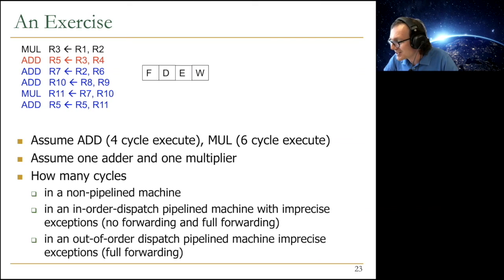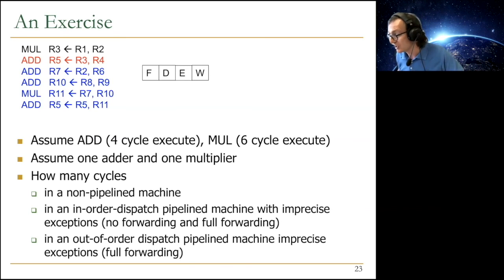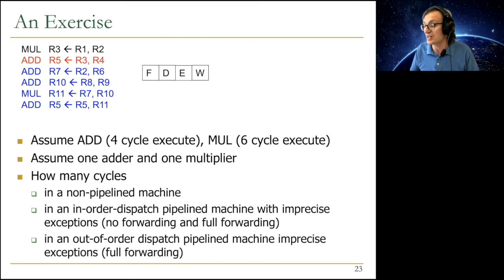How many memory accesses are handled? Is it now not possible to load something before it's written? So we're going to talk about memory accesses after we discuss the arithmetic instructions. Memory accesses are going to complicate things. Yes, I think you're foreshadowing some of the issues that may happen with stores and loads. For example, if you have a store instruction that's writing to an address that the load instruction is going to read from, that's going to complicate things.